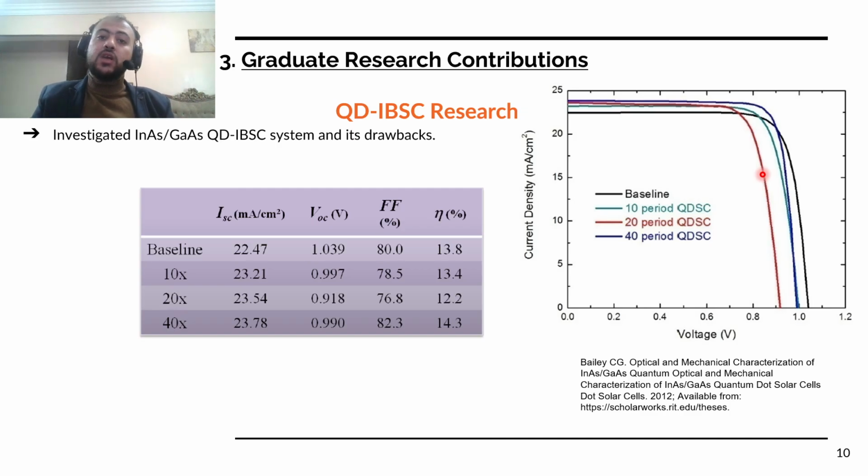The third reason is the high lattice mismatch between indium arsenide and gallium arsenide, which is 7.16%, or above 7%. This causes problematic structured growth, and also causes low carrier separation efficiency and low carrier extraction efficiency, because carriers usually get captured inside the quantum dots during transport.